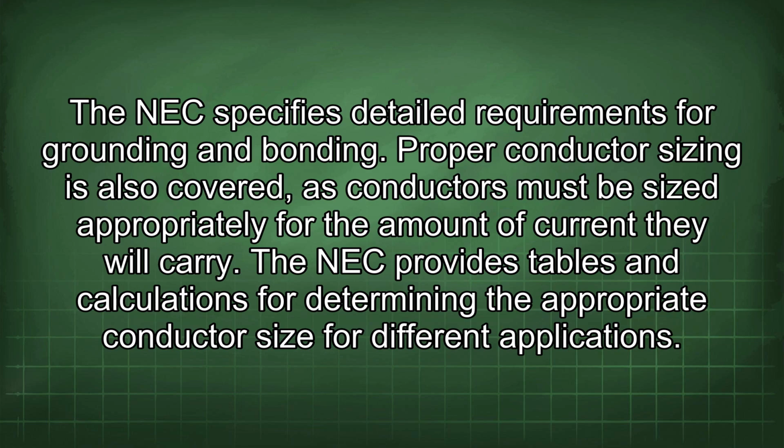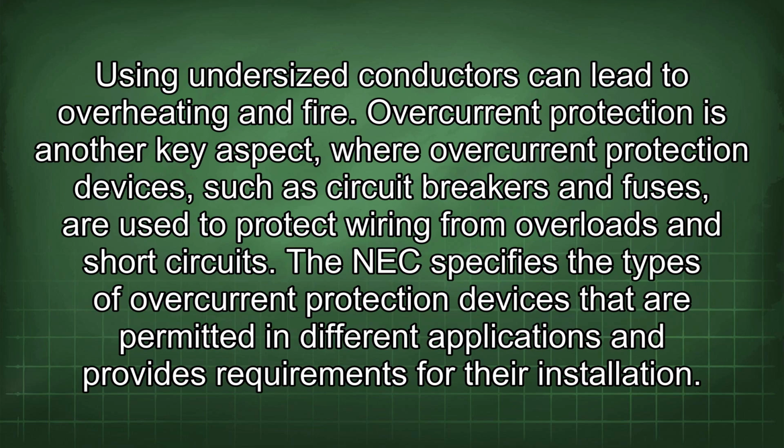Proper conductor sizing is also covered, as conductors must be sized appropriately for the amount of current they will carry. The NEC provides tables and calculations for determining the appropriate conductor size for different applications. Using undersized conductors can lead to overheating and fire.